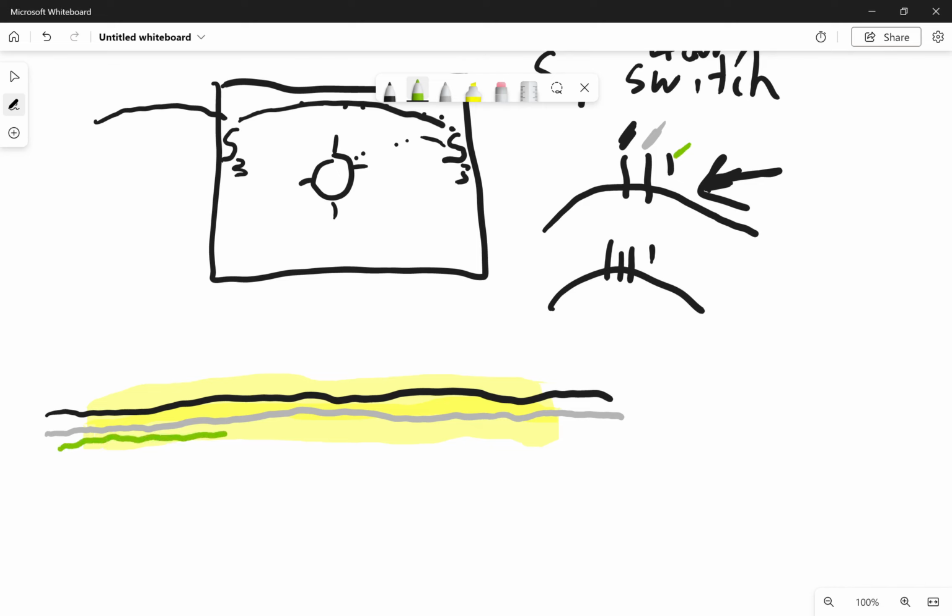And I don't have a copper colored line, so we're going to use green, right? Because if it had insulation on it, it would be green insulation. The green tells us that it is the ground. In Romex, that wire does not have an outer jacket on it, and so it's just bare copper. We're going to use green to represent that when we're doing these drawings.